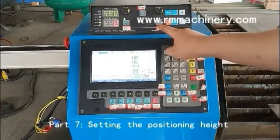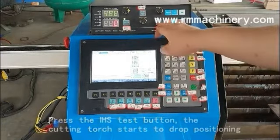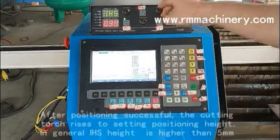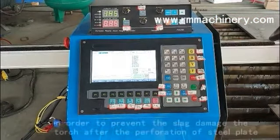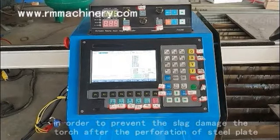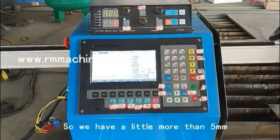Part 7, Setting the Positioning Height. Press the IHS test button, and the cutting torch starts to descend for positioning. After positioning is successful, the cutting torch rises to the setting height. IHS height is generally higher than 5 mm, in order to prevent slag from damaging the torch after the perforation of the steel plate. So we set a little more than 5 mm.